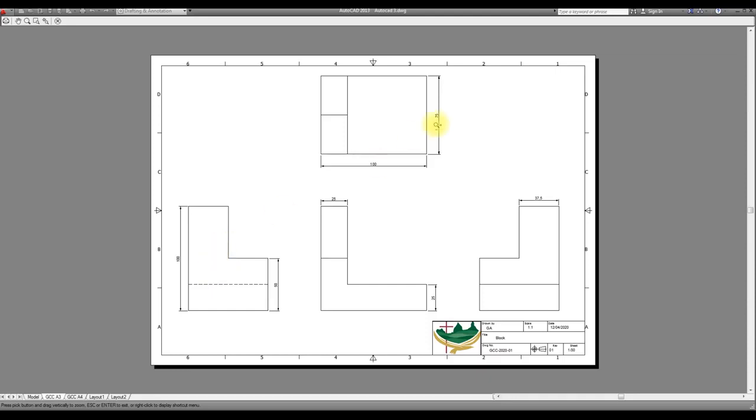They're not the colours. It comes out black and white on a sheet of paper. If you try and have a white sheet of paper with a yellow dimension or a red dimension, it's really, really hard to read. You're communicating to the fabricators. You've got to communicate in a manner that they can understand. It doesn't cause them any difficulty. Printing with colours makes your communication to the fabricator really hard. So it's up to you to make sure that it prints black and white.